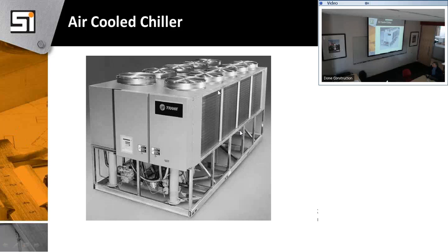There's limitations on another thing on Title 24, and I think they strengthened it up. They used to say no chiller over 300 tons to be air-cooled, because these aren't as efficient as water-cooled units. But so we have a bunch of multiple 200s and do it different ways. So now I think they just said no more than 300 tons of air-cooled chiller, period.